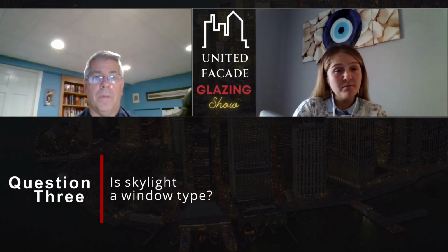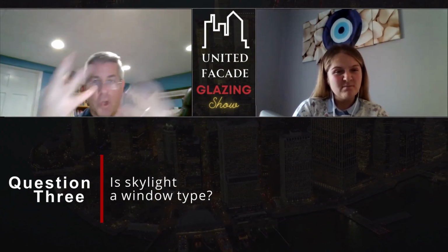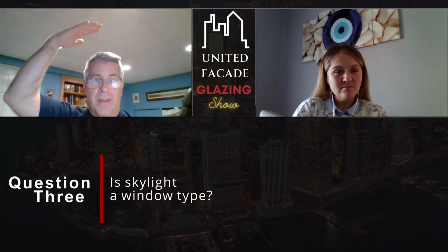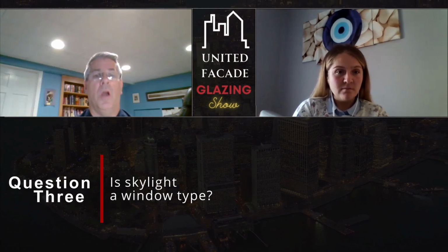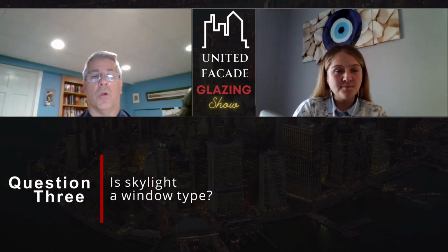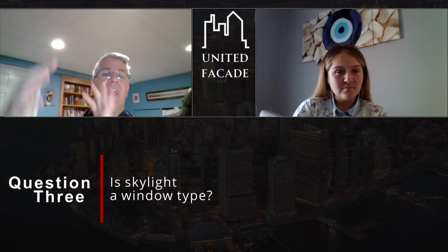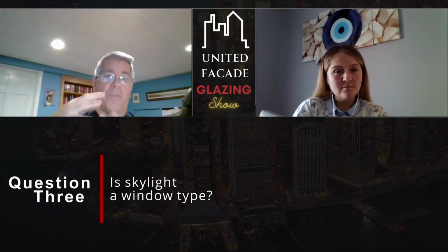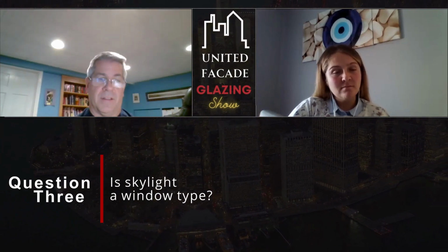Oh, that sounds good. Normal glass in a window, you break it, you get shards of glass that could fall down. Yeah. Picture glass over your head. If it breaks, you don't want that raining down on top of you. So a requirement of skylight glass is that it's the same type of glass that's in your windshield, called laminated glass. So if it does break, it's going to stay together. It'll be broken, but it will stay together. It's not going to fall down and leave a hole above you with glass falling down on top of you.